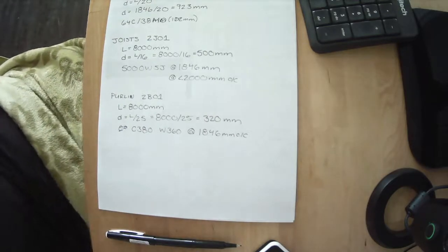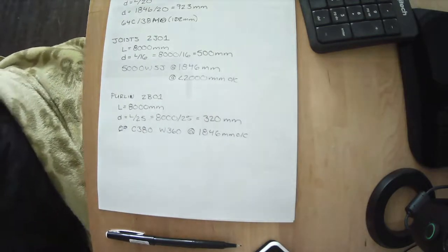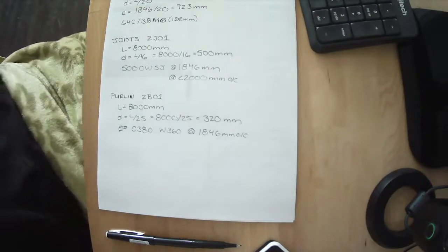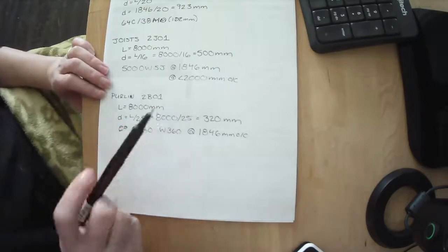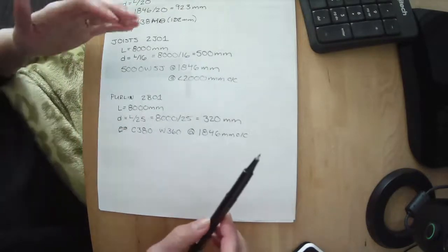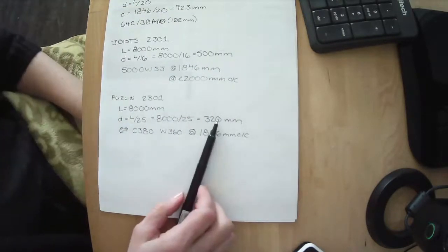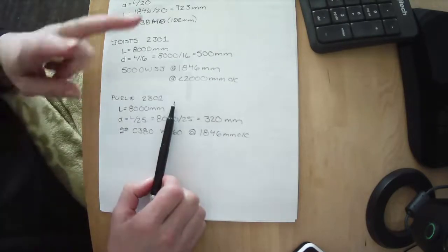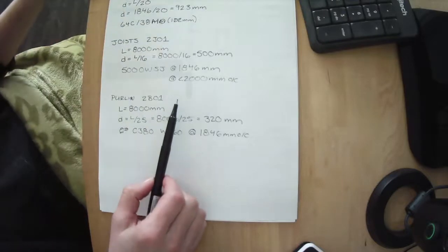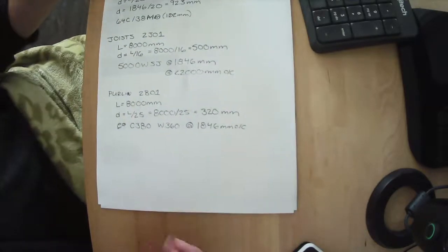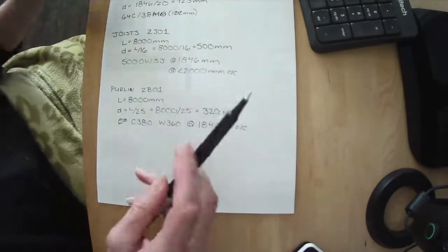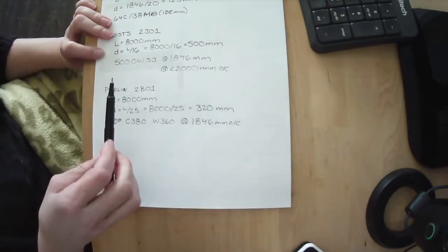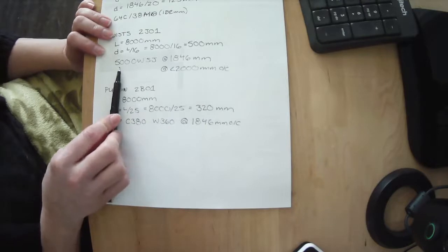Now, why would somebody use purlins versus open web steel joist? Well, I can't answer that. Every project is different. Often if you have a lot of them, the open web steel joists can be cheaper. For example, right now though, I know open web steel joists have a 2-year lag time. That'll probably catch up soon, but that was due to COVID accelerated construction issues. But a lot of them, these are usually cheaper.